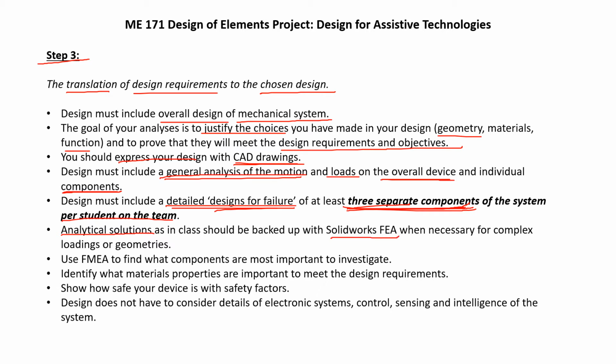Sometimes you may find, well, I really can't get as detailed with my analytical solutions, and I may have to make some big assumptions and simplifications when I'm doing these hand solutions as compared to what I can do within a SOLIDWORKS FEA. And you may find within the SOLIDWORKS FEA, some of these really detailed solutions, you're not quite sure if they're right. You might want to go back to that general hand solution you have and compare those two. So you're going to need the analytical solutions backed up with SOLIDWORKS FEA models as well. Now, one instance for these SOLIDWORKS FEA models, as I just mentioned, is when it gets complicated, for these complex loading and or geometries.